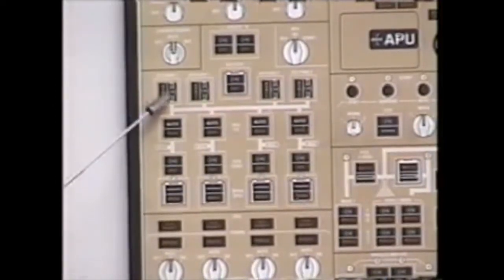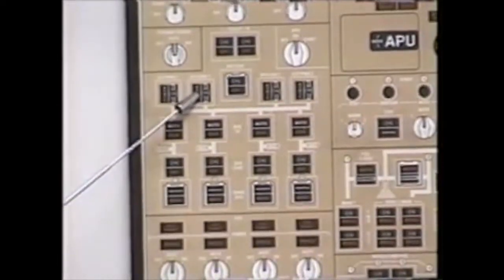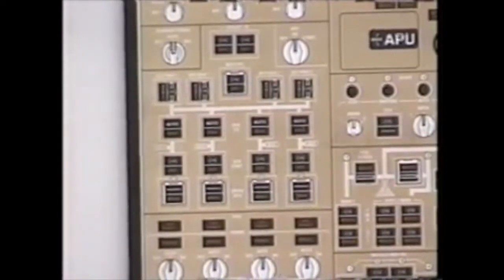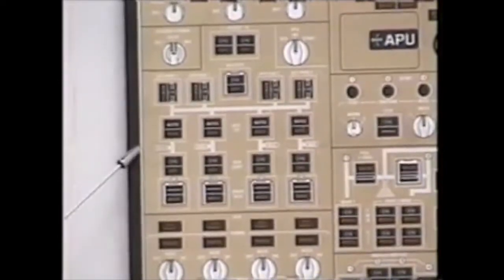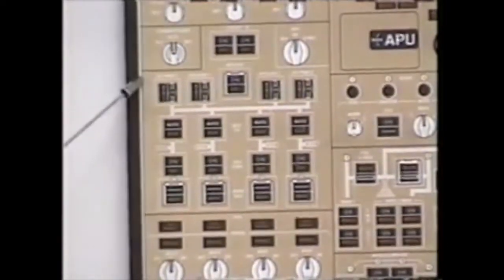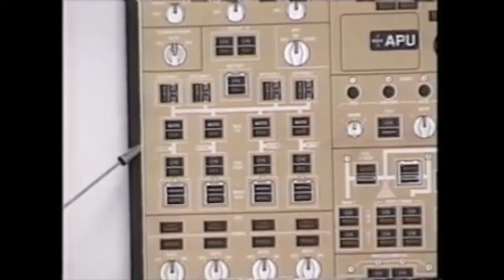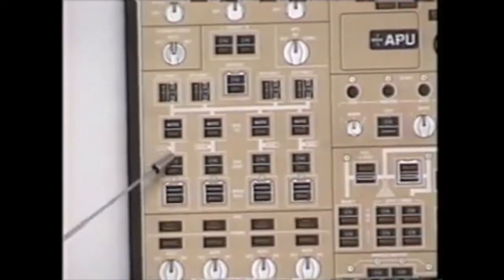If there is no light in this switch or this switch, regardless of the other status of your airplane, the ground handling bus is not powered. It is impossible to power the ground handling bus from external power number 2 or APU generator number 2. The bus in this location here, the service bus is what Doc calls it. It's called the ground service bus. However, the ground handling bus only works on the ground.